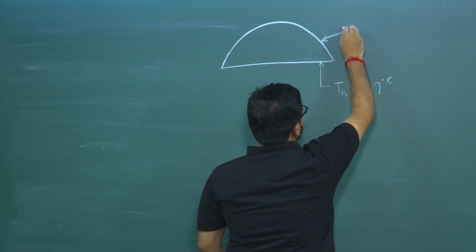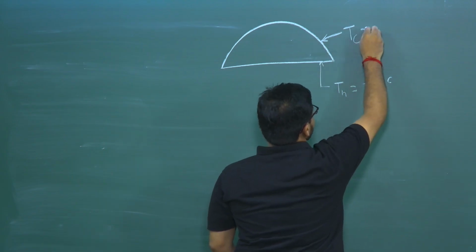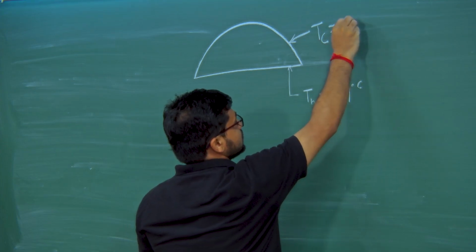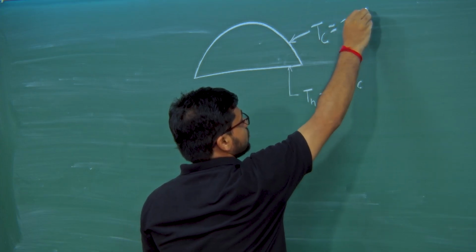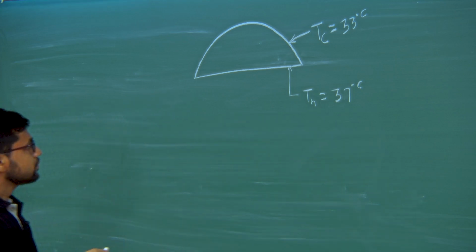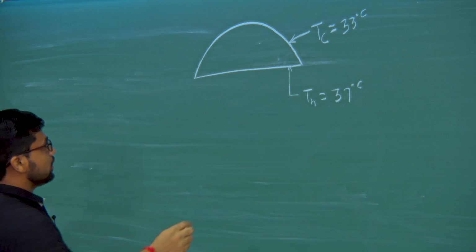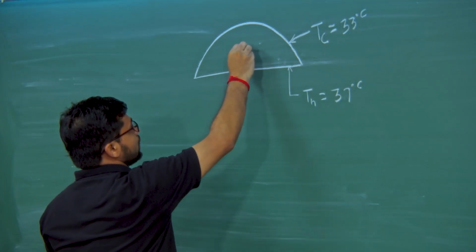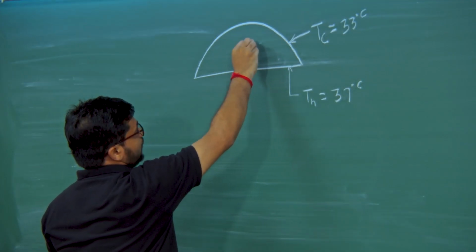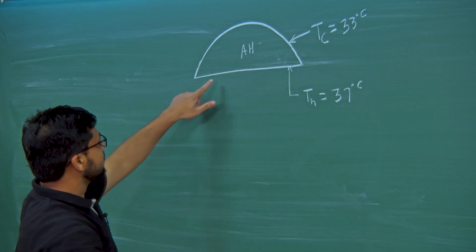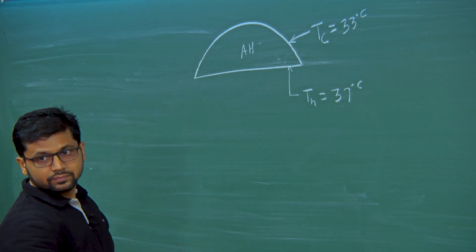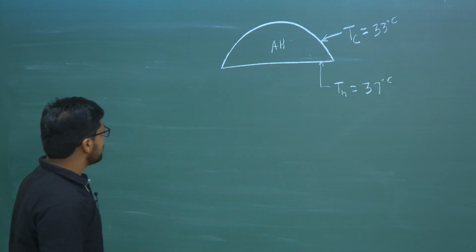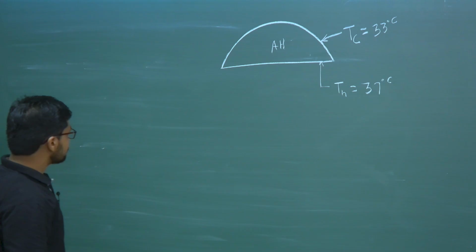So, the temperature of this surface was Tc, which was slightly less than the body temperature, and let us take it to be 33 degree centigrade. In the region between cornea and iris, aqueous humour was present, and the aqueous humour flows because of the temperature gradient between these two surfaces combined with gravity, because buoyancy is there. So, that will make this fluid circulate inside the anterior chamber.